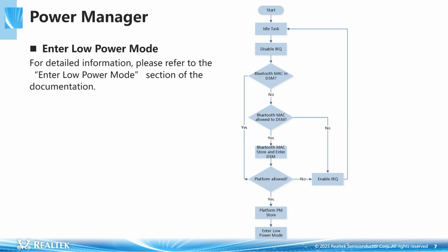Most of the time, the system is in an idle state and only necessary data needs to be retained for system recovery. Components such as the clock, CPU, peripherals, and RAM can be powered off to reduce system power consumption. When there are any events to be handled, the system will exit from low power mode. The clock, CPU, Bluetooth, peripherals, and RAM will be repowered on and recovered to the previous state before entering DLPS, and then respond to the wake-up event.